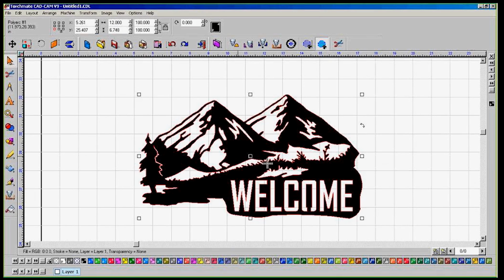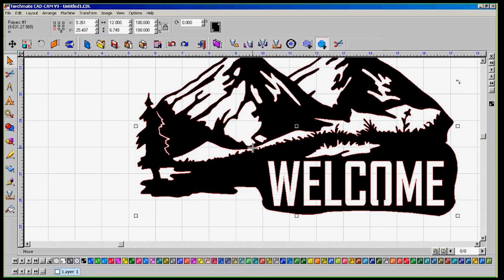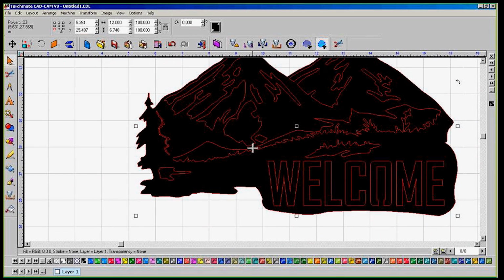So I'm going to go to Basic Cut. I'm doing it as a plasma. I'm going to go to Climbing, and I'm going to give it a feed rate of 100. Now, since it is an online toolpath, it doesn't get a lead-in or a lead-out. And I'm going to press OK. So I don't have tool diameter on. So here's our online toolpath that it generated.